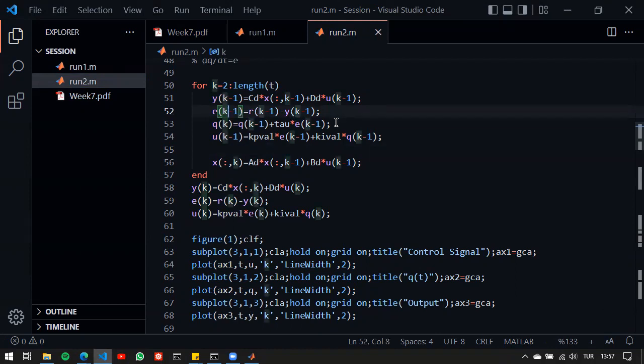Other than that, you should also note that we have implemented a digital PI controller. This is not a continuous time PI controller. This is a digital PI controller. We've used the P gain and the integrator gain, and we've just used numerical integral and the error itself. This is a digital controller. So this can also exemplify the implementation of a controller, because we might have a circuit, a DSP or a certain digital circuit that calculates all of this. It uses the measurement and generates the control signal and applies it back to the system. So this could be the case.